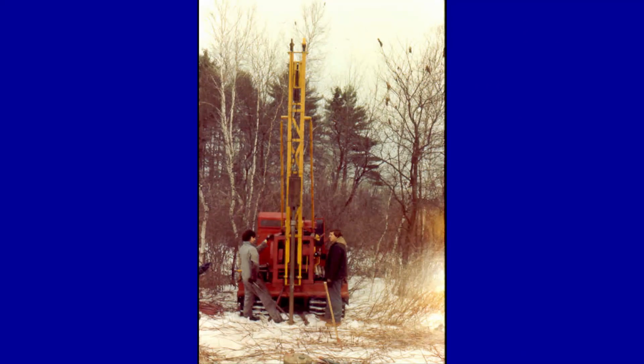We still find that the old technology of drive and wash is the least expensive and the most effective way to determine what the stratigraphy is within an area that we believe has sand and gravel potential for development of groundwater. Here we're talking about a bombardier mounted drilling rig with a hammer being raised and lowered that will drive 2.5-inch diameter Schedule 80 steel pipe into the ground.